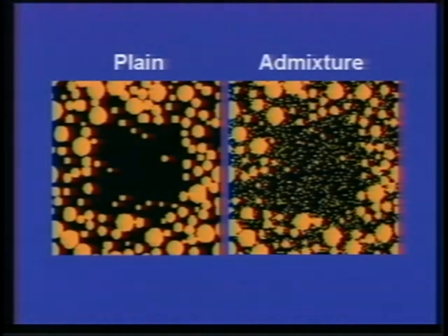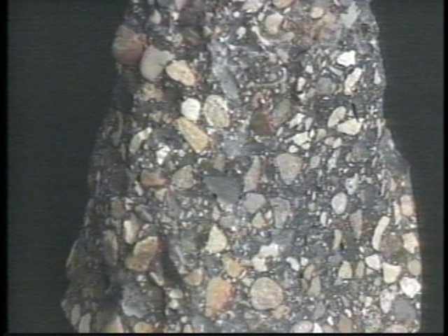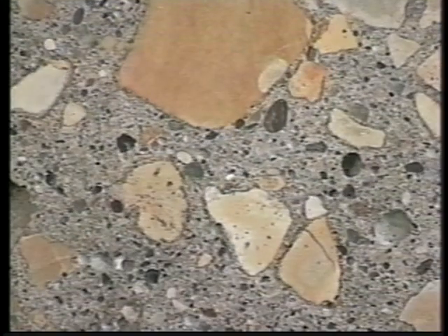The picture on the left shows the ITZ in a plain cement concrete. The picture on the right has 20% of the cement replaced by a mineral admixture. Notice that the small admixture particles are packed closer to the aggregate surface. Now 70% of the cement has hydrated. It is easy to see that there is more brown solid material and less black porosity in the model with the admixture. This makes the ITZ denser and stronger. Fractured concrete containing silica fume shows crack patterns that run directly through aggregate grains rather than around them. The ITZ regions are no longer the weakest links in the concrete microstructure.